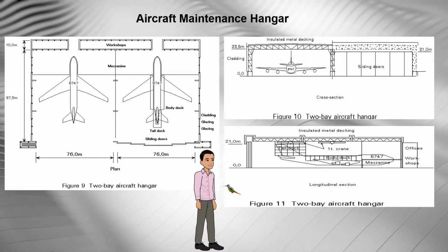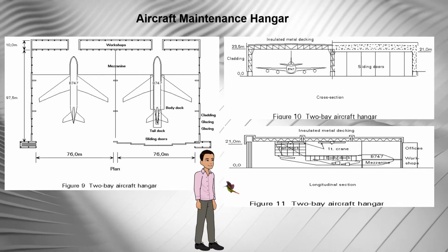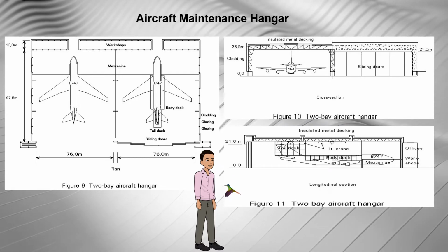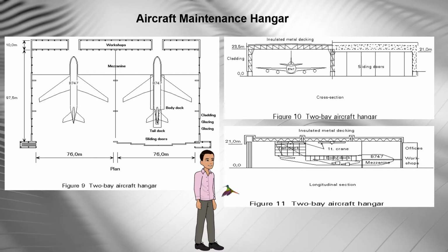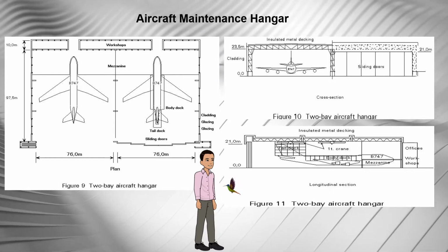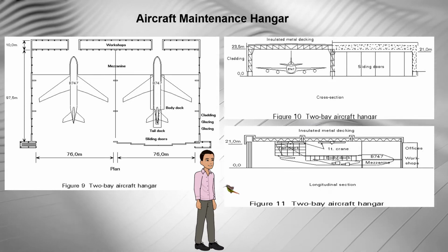If bunching space for the doors overlaps the door opening, the bay width is increased correspondingly. Some hangar doors are only 14 meters high with a 7 meter high tailgate, or they may have a vertically folding 21 meter high center section.